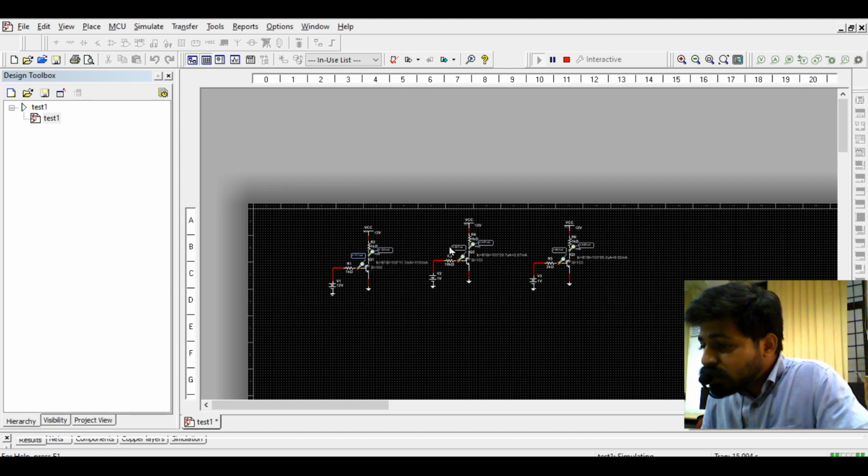So the first thing we do, before you give the input signal to the circuit where amplification is needed, is design a biasing circuit such that the transistor is brought into the active region. In the process you can go with any method, either adjusting the base biasing circuit or the collector biasing circuit. So these are the two ways you do the biasing and make the transistor operate in the active region.